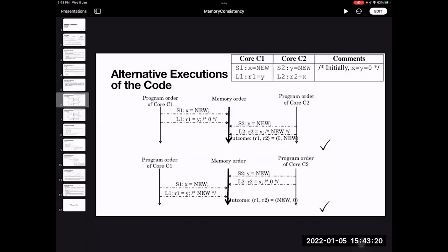If you want to exploit that, then we have to come up with the store buffer. But once we come up with the store buffer, we have to relax some conditions. From sequential consistency, by relaxing some conditions, we go to total store order. If we further relax some conditions, we go to relaxed consistency models, and so on. There are many consistency models discussed. But generally now, if you want to use all the hardware optimizations, you better go for a relaxed consistency model.